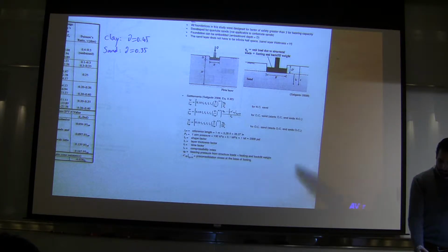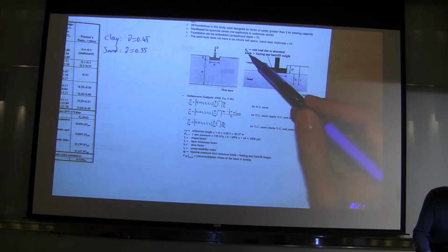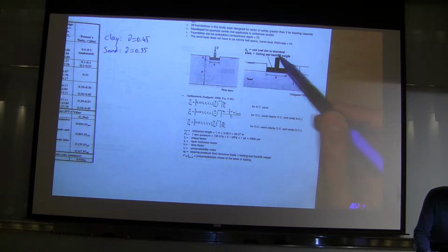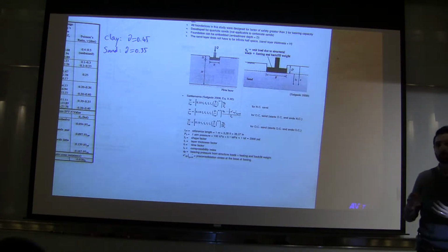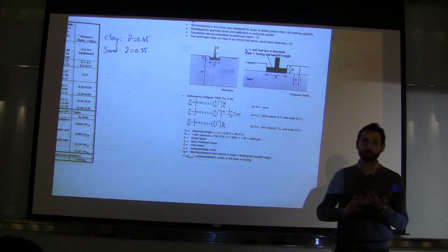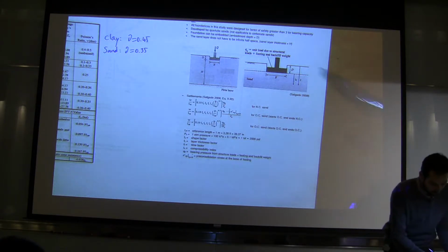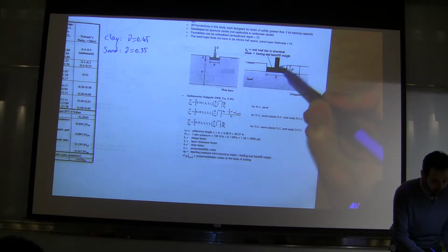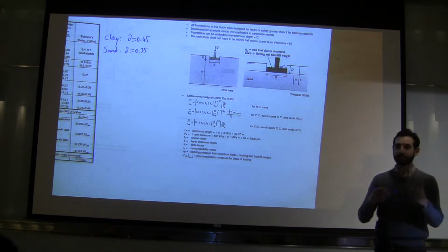There are a few variables that are defined on this plot on the right side. So that's the embedment depth. QB is the unit load due to structural load plus footing and backfill weight. So the load that you use in these equations as QB is the weight of the foundation, weight of the structure, and if you're going to backfill on top of the existing, so if you want to fill this area with a backfill, which we may or may not do, but in some cases you may end up doing, you have to add that load on top of it too.